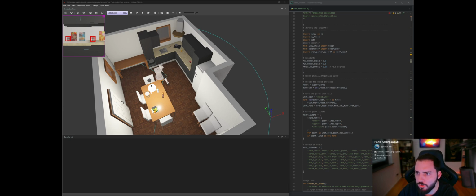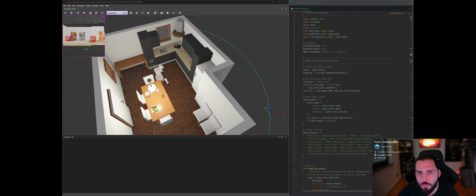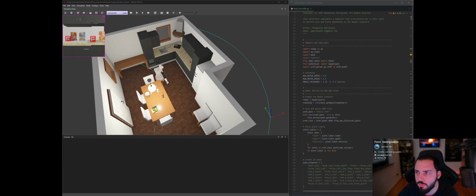The system architecture follows a modular design pattern with the behavior tree as its backbone. Some of the key imports are, of course, py_trees for that behavior tree. The ikpy Python library is used for inverse kinematics, also for calculating where the end effector is on the joints. URDF parser is used to parse the robot URDF file, which is a file that contains all the information of what is on the robot or what makes up the robot's body.